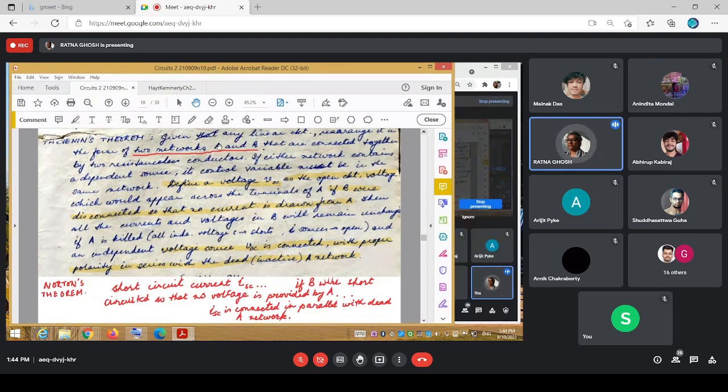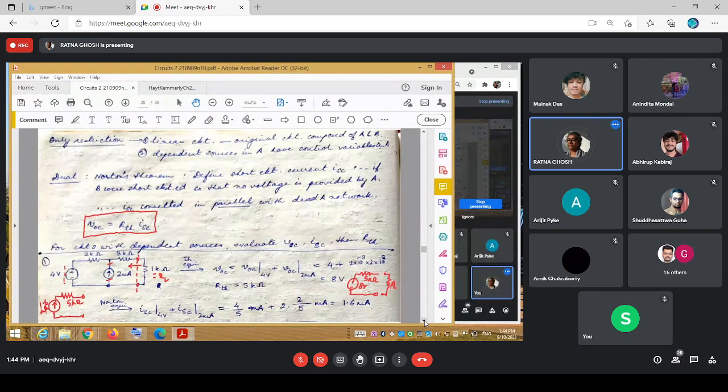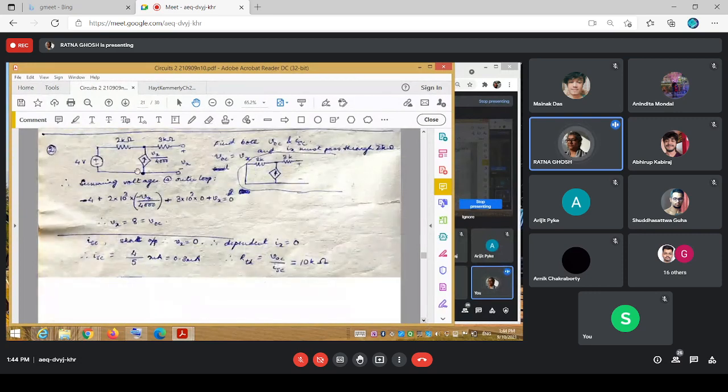Network meaning that part A or part B. So in that sense, it is there in that A part. This is just the A part which is drawn. And because there is a dependent source, you can't find a dead network per se. So your option is now to find out both VOC and ISC and interpret R Thevenin or equivalent R Norton from these two. Okay.